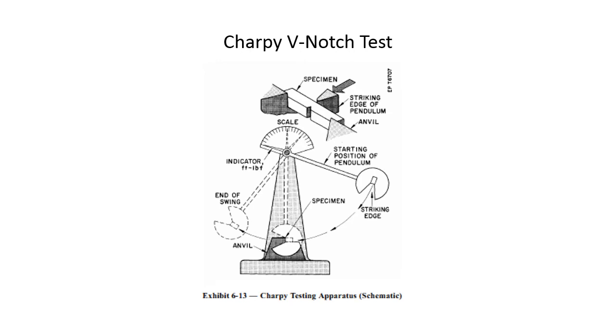Charpy V-notch test. You can see how you take your specimen after it's cooled to whatever temperature and you put it in the anvil, and you can see where the striking edge of the pendulum hits on the opposite side of the specimen from the notch that you've machined into it, and you have the starting position of the pendulum, the striking edge, it comes down, it whacks that test specimen,